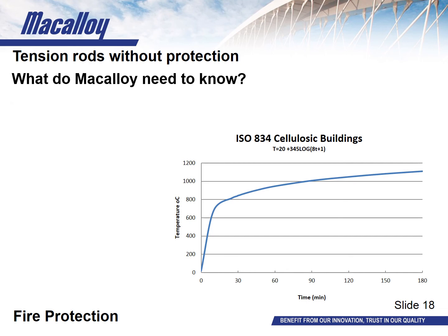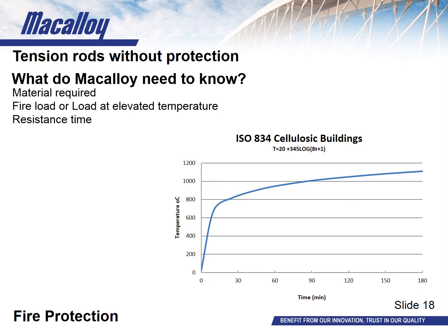To determine this, we need to know the following. Which material you need to use. So are you planning to use a carbon or a stainless steel, as that does make quite a significant difference. We'll also need to know the fire load or the load at elevated temperature. And finally, we'll need to know the resistance time. So as previously stated, this could be anything from 15 minutes to 120 minutes.